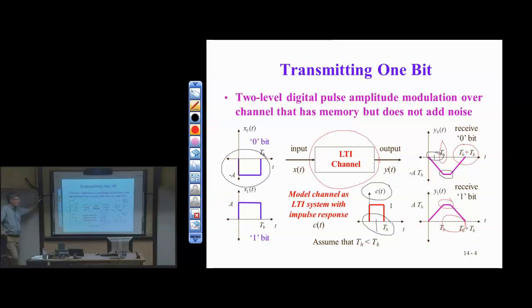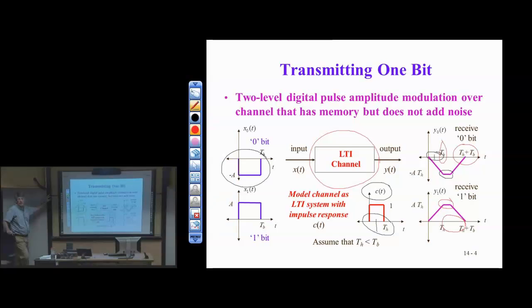So if the average value over the symbol duration is 0, I don't have a good way to determine the bit. Assuming that the probability of sending a 0 is the same as the probability of sending a 1, I really don't know. I can flip a coin, pick a bit, or just always choose 0. So you can always force the comparison instead of being, is it greater than 0 or less than 0? You can bias that comparison and say greater than or equal to 0 or less than or equal to 0 to bias that case of 0 one way or the other.